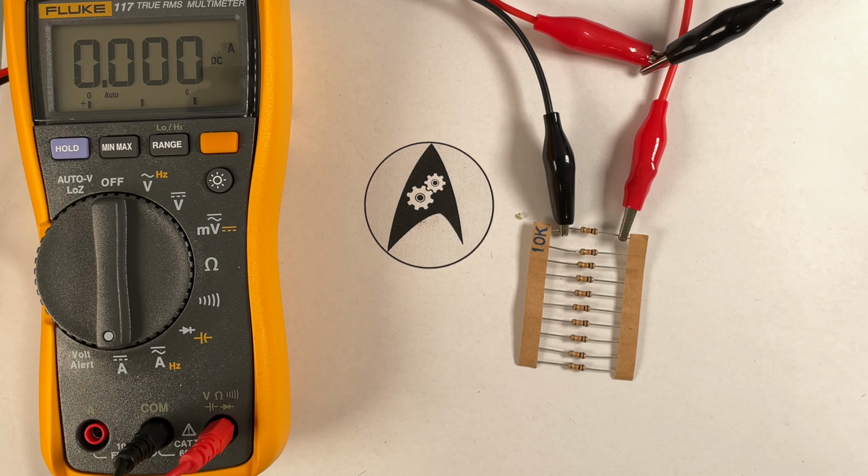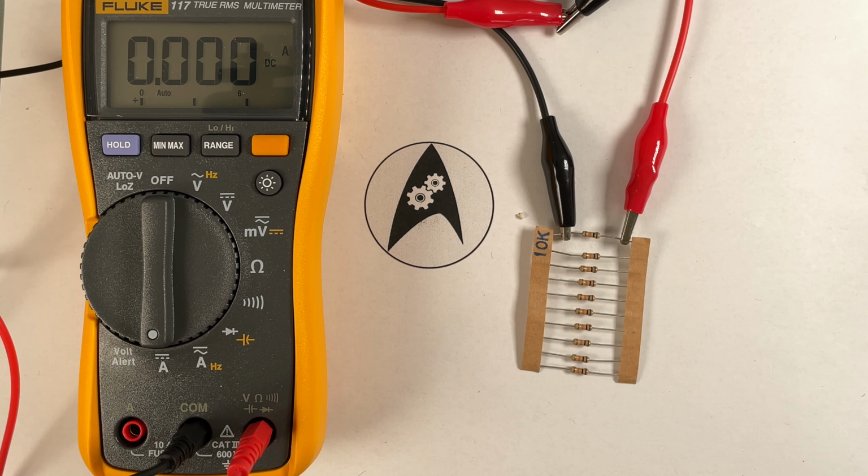So we again have a closed circuit. Now before we start the actual measurement, let's take a quick look at this cable here. We have used it for measuring the resistance of the resistor and also for voltage measurement, but as you can see there is no amperage symbol. This is only on the left side here. The reason behind this is that this multimeter prevents against a large current flow by having an appropriate fuse inside.